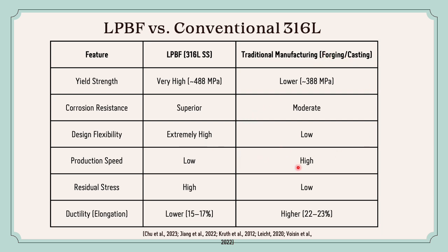methods. However, LPBF also has some limitations. The production speed is generally lower, and the residual stress tends to be higher. The ductility is slightly reduced compared with conventionally manufactured 316L. Therefore, LPBF provides excellent performance and design freedom, but process optimization and post-processing are often required to achieve the